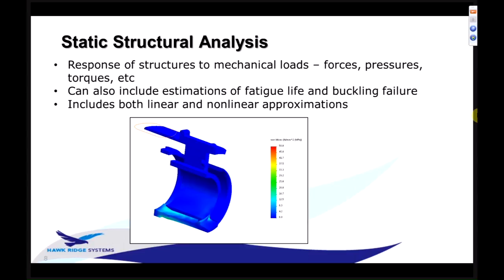We can blend this up into estimations of fatigue based on those static loads, and also look at buckling behavior. We can include linear and non-linear approximations of situations. Linear approximations use linear material models, they assume small deformations, and they assume static loading.